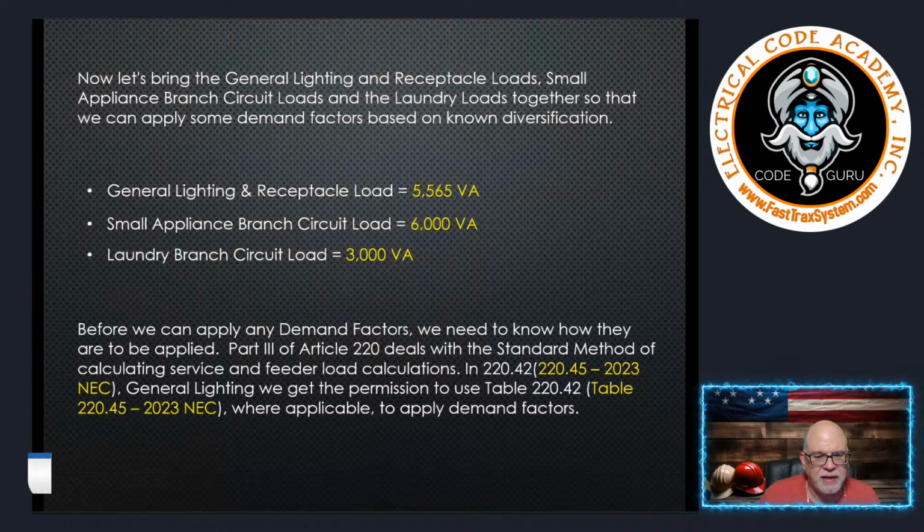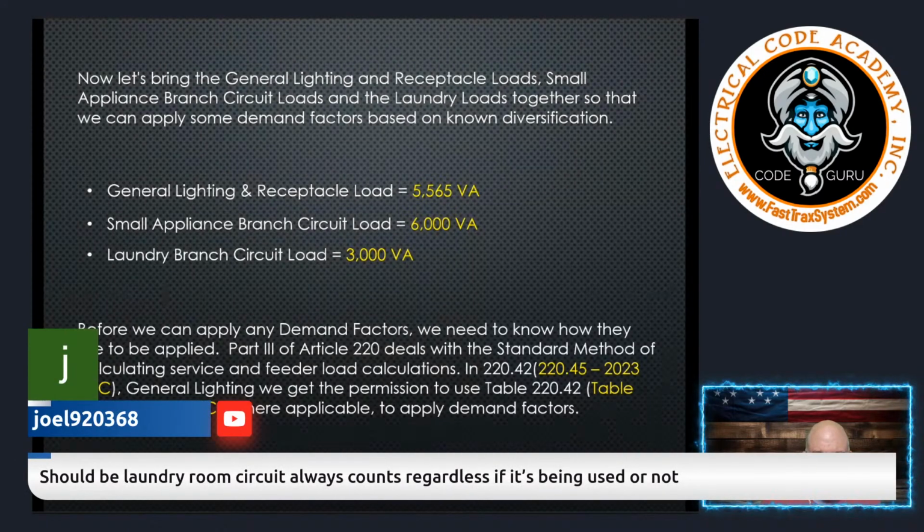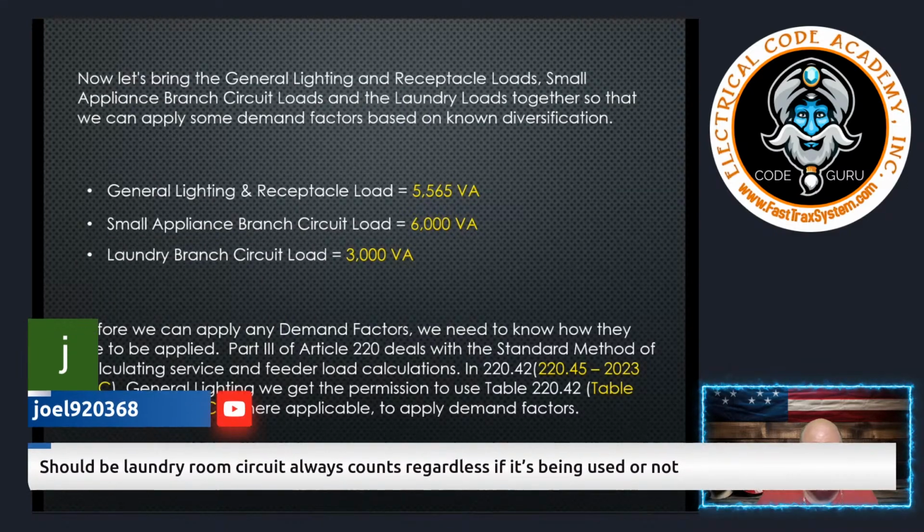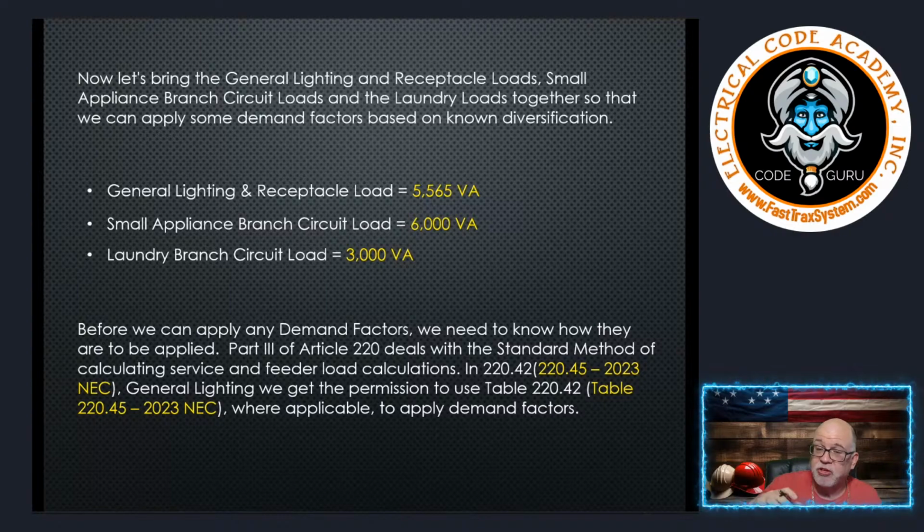Let's see here. Question we had: should the laundry room circuit always be counted regardless if it's being used or not? You have to have a laundry circuit, period. Unless you're dealing with a multifamily dwelling that has a laundry facility on site that is available to all of the tenants or all of the renters, then it doesn't matter whether you use that laundry room or not. You have to have at least one 20 amp laundry circuit. Okay? Got to have at least one.